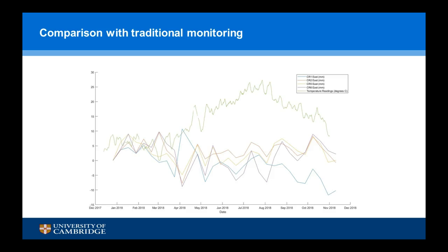The reason I put in this slide was particularly just to notice a few interesting effects. One, this is the temperature, and these are all the various readings from the different prisms. There's a couple of points that end up being discarded. This one turned out to have various atmospheric effects that couldn't be corrected for in the image processing. And generally speaking, the readings are taken every 11 days, which is a much coarser rate of reading than what we would generally, as civil engineers, be used to seeing.